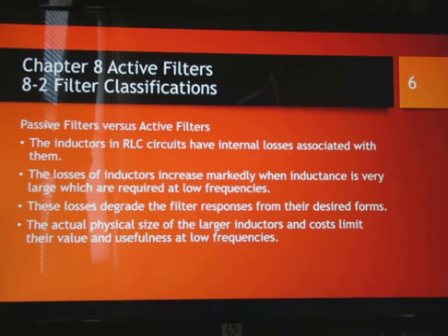An RLC, or passive approach, uses devices which might be considered imperfect, with large tolerances. They can get large in physical size depending on the frequency range you're working in, and the cost can be a factor. And getting specific values is difficult on some devices, such as inductors and capacitors. Some frequencies are better suited for passive devices, and that hasn't changed. Low and very low frequency spectrum is better suited, though, for active filters, and that's becoming more common. However, passive filters are still dominant if we get into the radio frequency range.